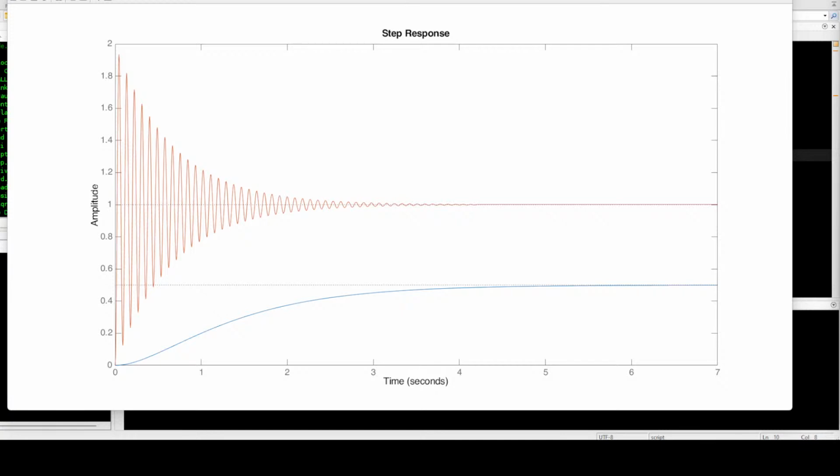Where's the closed loop tuning? Turn on P only mode, turn off integral and derivative, and turn up KC in increments until you get stable, sustained, periodic oscillation in the output. Mark this critical value as KU, the ultimate gain, and note the period of oscillation.